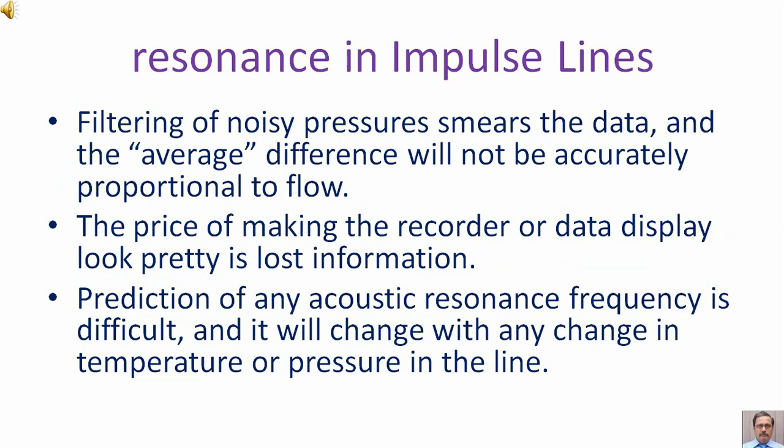Filtering of noisy pressures smears the data, and the average difference will not be accurately proportional to flow. The price of making the recorder or data display look pretty is lost information. Prediction of any acoustic resonance frequency is difficult, and it will change with any change in temperature or pressure in the line.